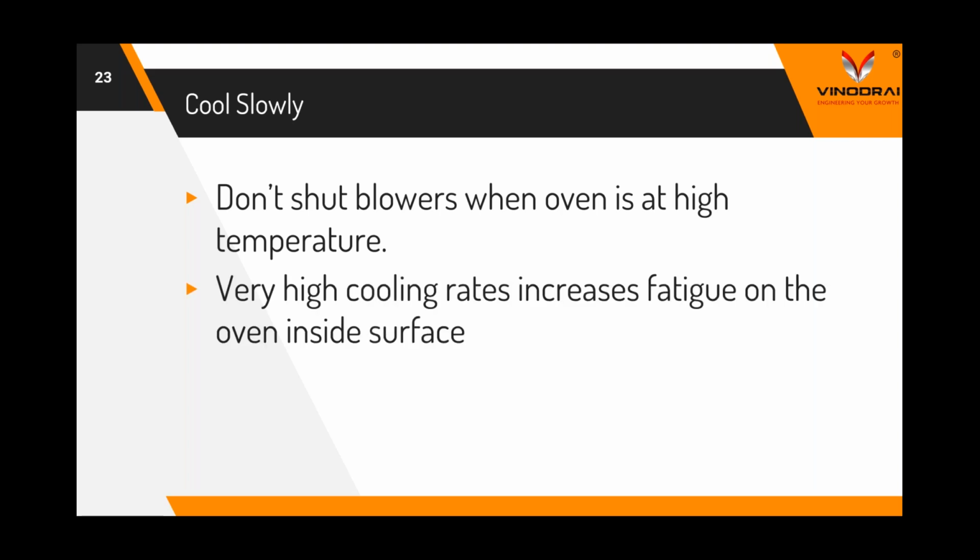Also, a very high cooling rate can lead to fatigue on the inside surface of the furnace, which the furnace might not be designed for, and it would reduce the life of your oven. So, cooling slowly is always a good idea.